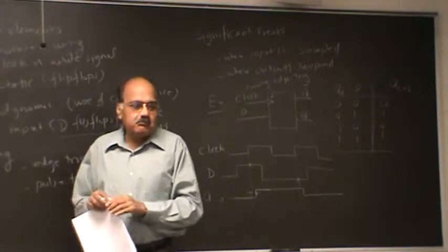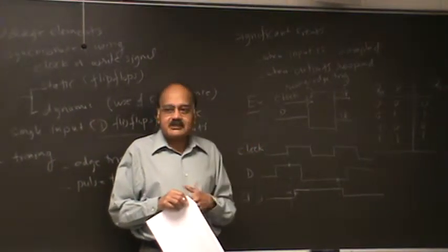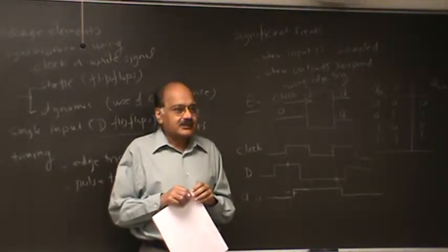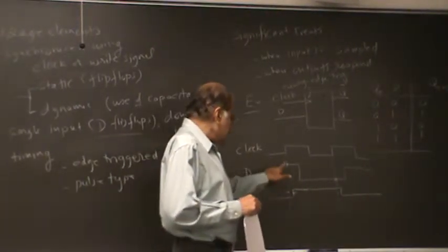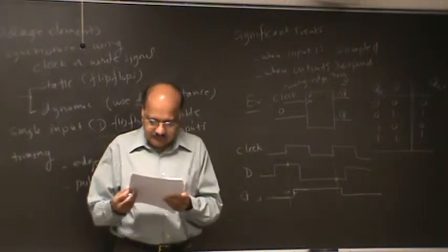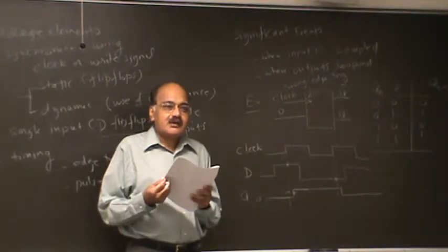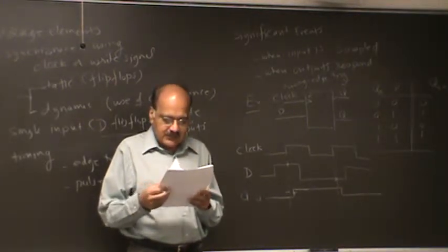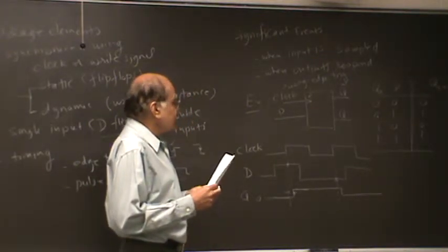So there are some mechanisms for doing some design so the probability of such synchronization failure is minimized. But basically, the idea is that during the time when an input is sampled, it should be stable. Now that has an implication on the clock frequency of the circuit, which I will mention later. Any questions about flip-flops?